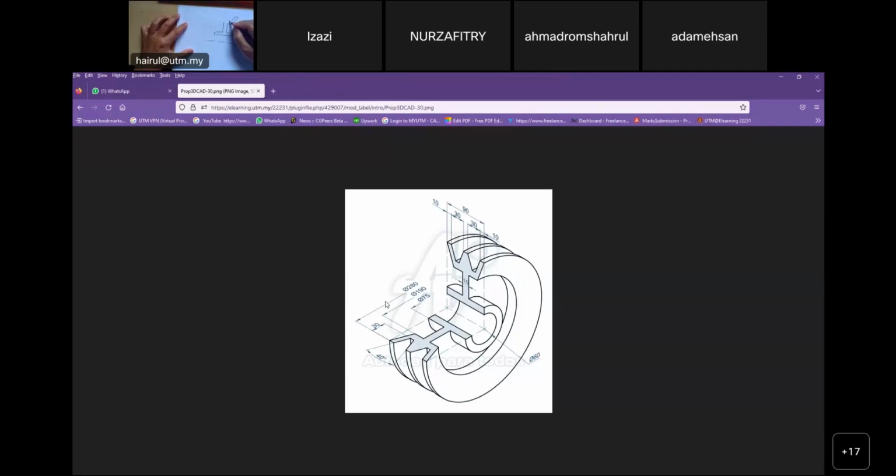Kena draw this shape in the right plane lah. Kalau you want to go for this orientation, so you need to draw this profile line. Boleh nampak saya punya ni, this profile I shaded. Yeah, I hashed this profile to be revolved at this center line. Center line given here, from here the radius is 30 because the diameter of the whole thing is 60. This one is 30. So you must know all the dimensions given. So you just simply draw the profile and you revolve it. So it becomes this wheel shape.